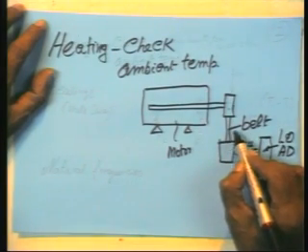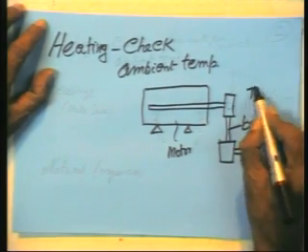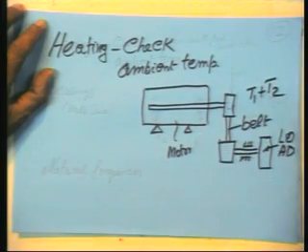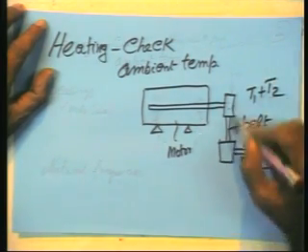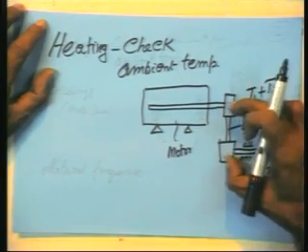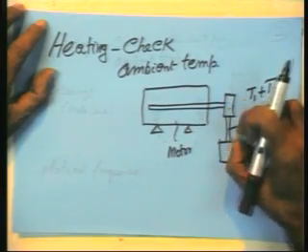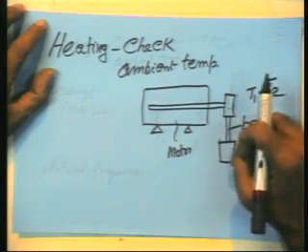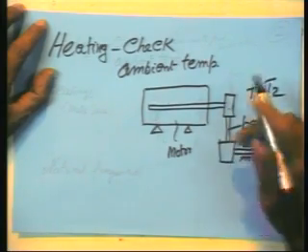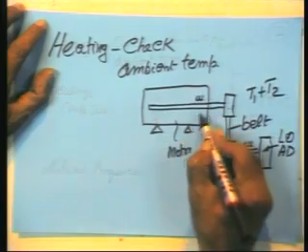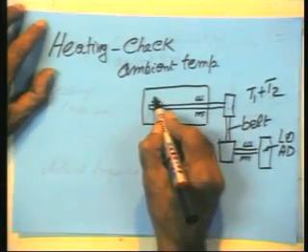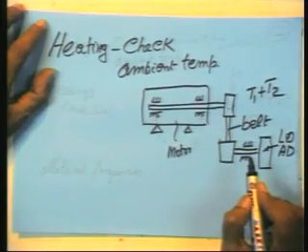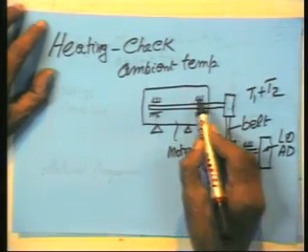As you are all aware, the belt will exert a tension T1 plus T2, where T1 is the tight side tension and T2 is the slack side tension. There will be a tension in the belt which will tend to pull these two belt pulleys together. In gears also, there is going to be a radial force in gear pairs. Remember that. Now that will end up loading the motor bearings or gearbox. It depends on whether you are using a motor directly or you have a gearbox also attached. It will end up loading these two.